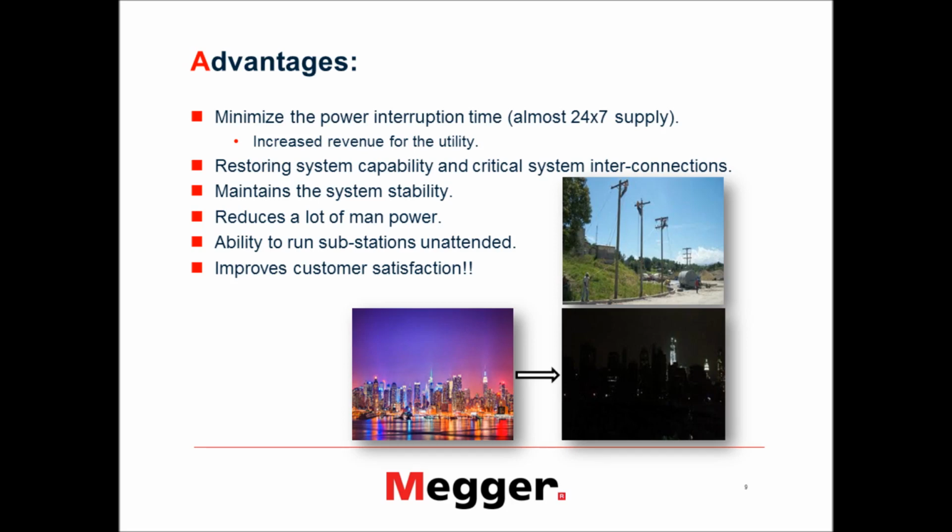One important thing is it reduces a lot of manpower, because imagine there is no automatic reclosing mechanism. So even a transient fault, or any fault for that matter, will open your circuit breaker, and there should be a manpower who goes to that specific circuit breaker and manually closes it. And there are numerous faults, hundreds of faults occur in a day in a given area.